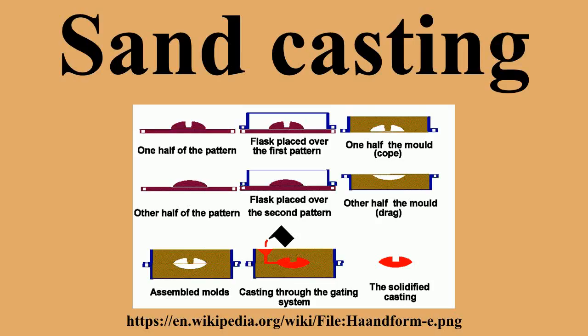Chills. To control the solidification structure of the metal, it is possible to place metal plates, chills, in the mold. The associated rapid local cooling will form a finer grained structure and may form a somewhat harder metal at these locations. In ferrous castings, the effect is similar to quenching metals in forge work. The inner diameter of an engine cylinder is made hard by a chilling core. In other metals, chills may be used to promote directional solidification of the casting.